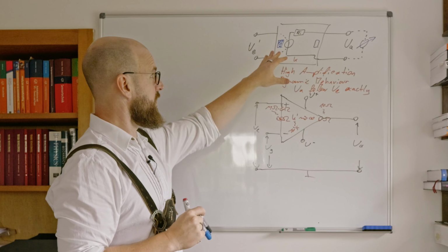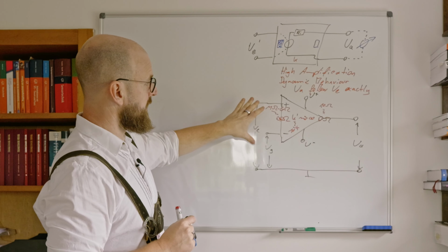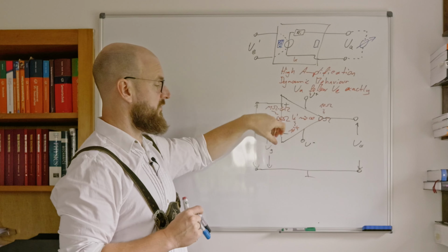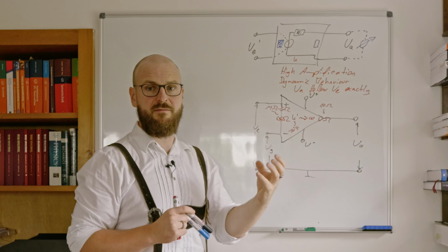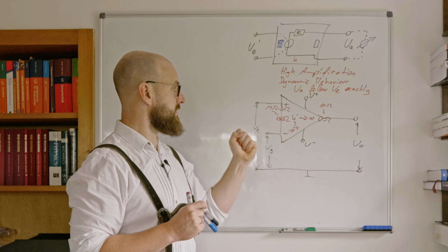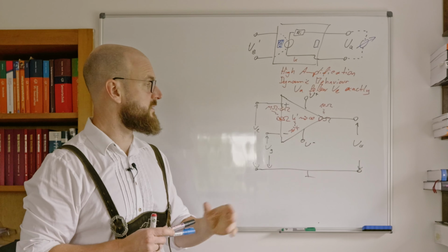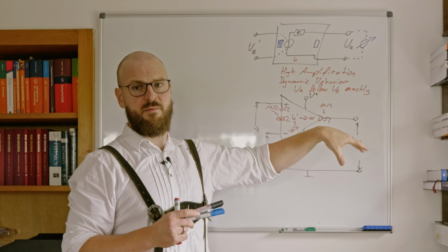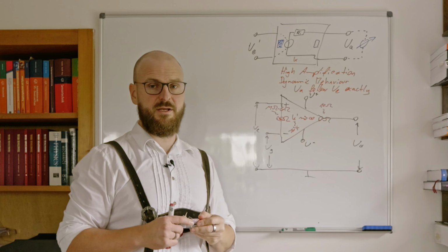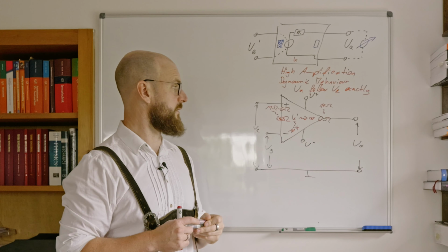That's fine, because we have a small signal over here, so we have a very high input resistance. You can think of that as a measurement device with a very high input resistance, so that's nice. That reduces our systematic errors. And on the other side, we have a very low output resistance, so we can use any measurement device over here to get the output voltage of our operational amplifier.